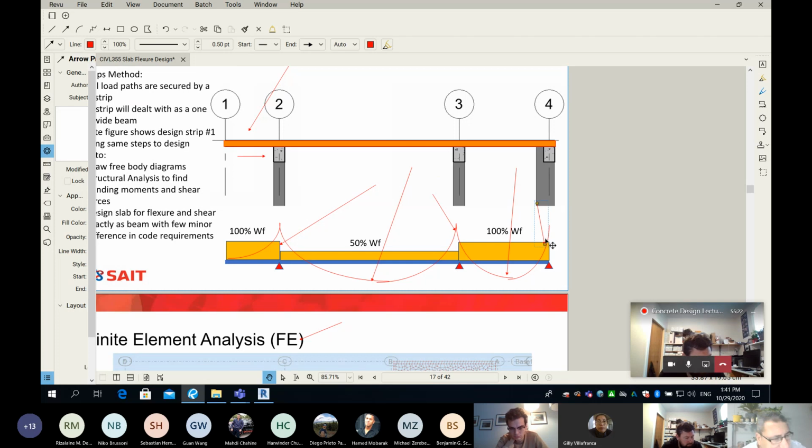You can see the process: because we have so many bending moments, I have to design more than one section. But really, as a big picture, if I'm able to convert my design strip into a free body diagram with all dimensions, and I am able to add the loads, I can use SAFI to find my bending moment. And once you know the bending moment, then you can find the area of steel. Are you guys following so far? Yes, sir.